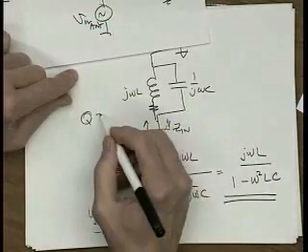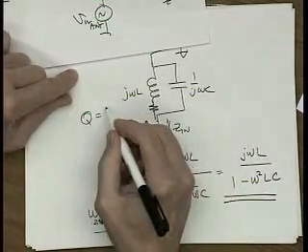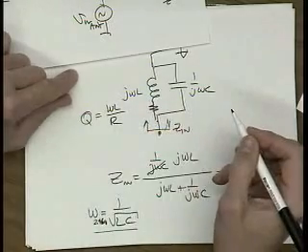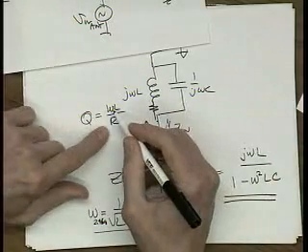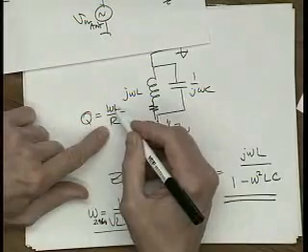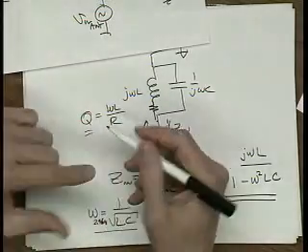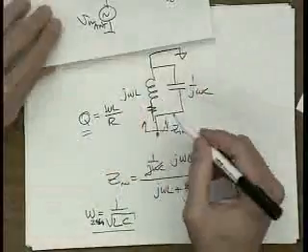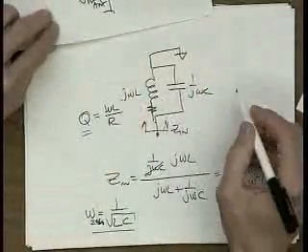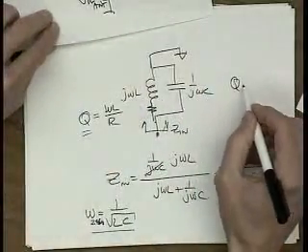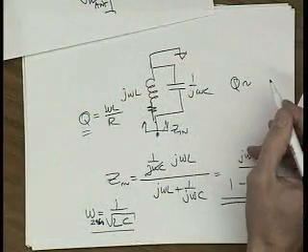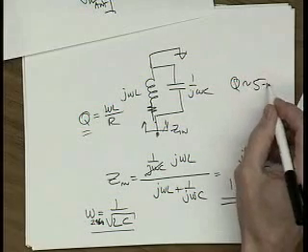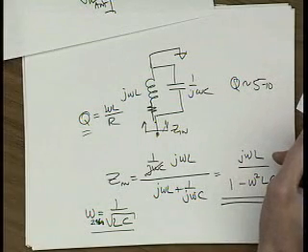And the Q of the inductor is basically omega L over R. So as R gets small relative to omega L, this Q value gets larger. What do you get in a standard process? This is coming from the resistance of the wires and so on. Qs at 2 to 5 gigahertz are typically on the order of 5, maybe up to 10, something like that.